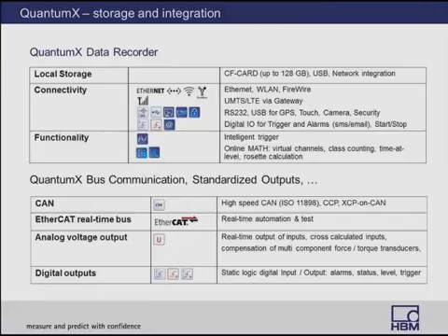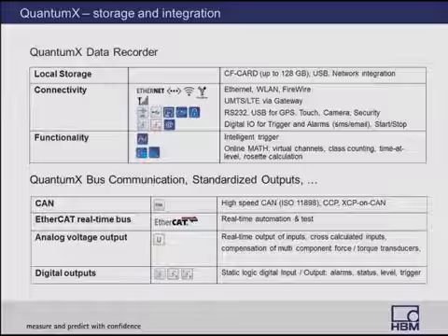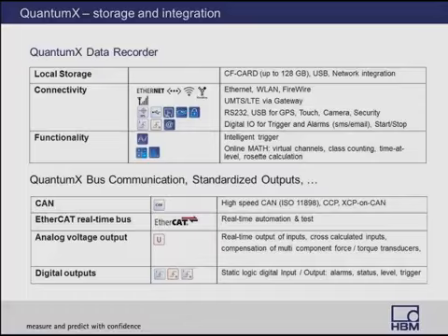But one of the biggest advantages of QuantumX is, of course, onboard mass channel, which means as the data is coming in, you can make real-time computations of certain kind and class deterministically on that data that's coming in. And this involves various types of peak measurements or addition or subtraction. And in some cases, using the QuantumX CX22 module, you can also do analysis of your stress versus strain, such as class counting, rosette calculation, time at level, and various virtual channels.